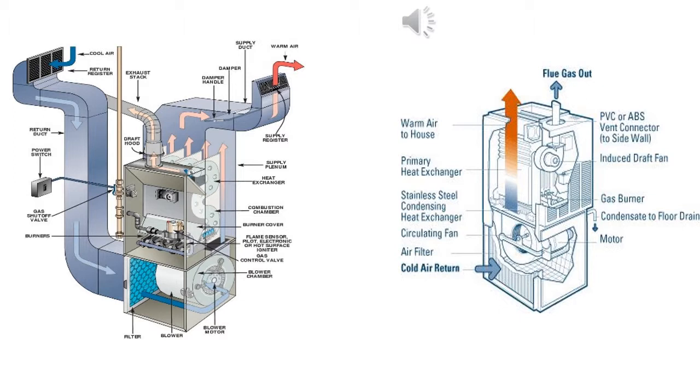The non-condensing furnace is still able to be vented out a chimney and will have a metal flue pipe, but on a condensing furnace they must be vented with a plastic flue pipe. So if you look at the two pictures, you will see some things that can tell you which furnace is a non-condensing furnace and which is a condensing. One of the first clues would be what type of vent pipe is used. Another clue would be the condensate line on the condensing furnace.